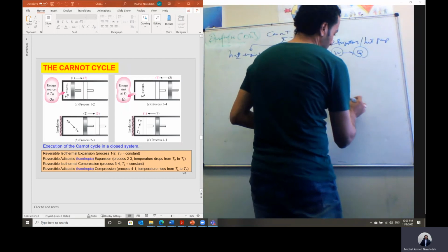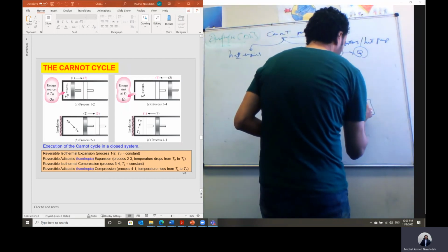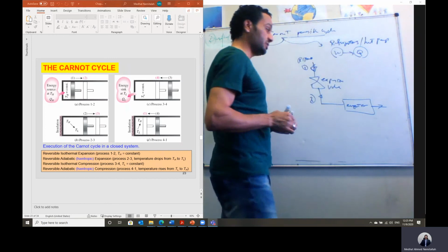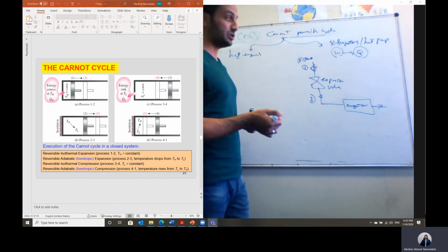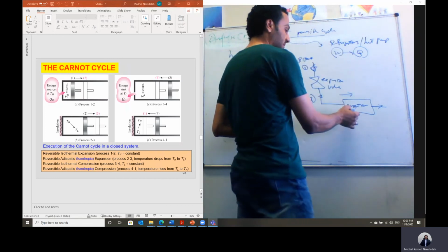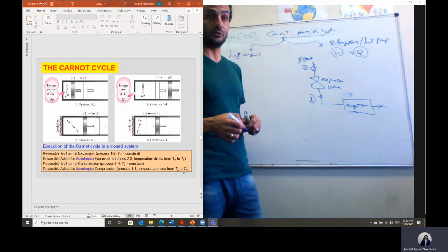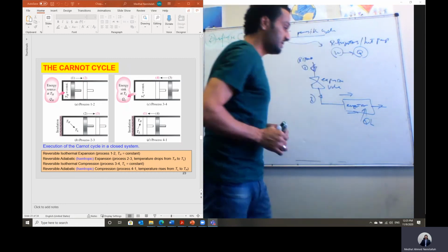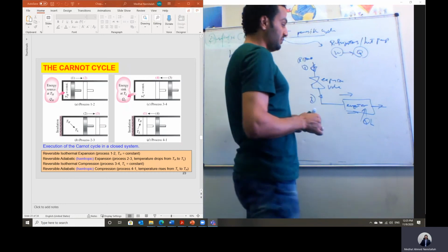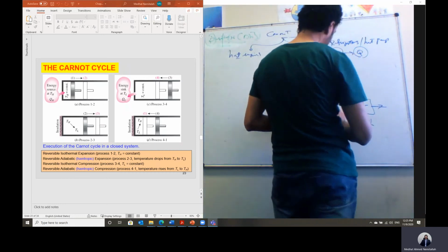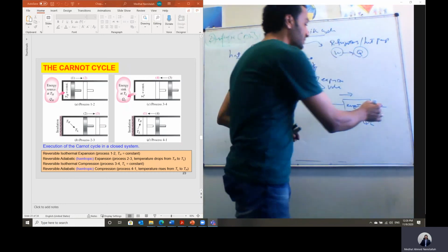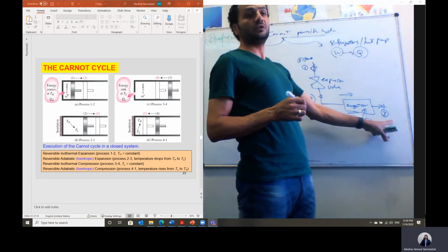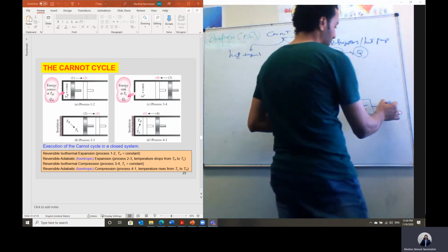Then we can pass it inside the evaporator, which is the food compartment in case of a refrigeration system, or in case of air conditioning, we pass the area around the evaporator so that it can absorb heat. So in this case, heat Q low is added at low temperature to the system. The Freon will be converted from state 2 to state 3, from liquid to vapor at state 3.